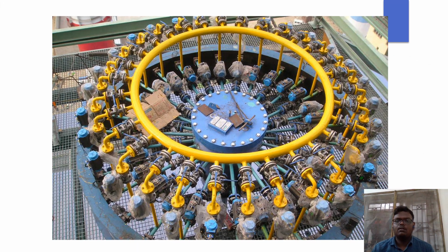In this picture, we can see the pulverized coal injection mechanism. The PCI method is based on the simple concept of primary air, which is the conveying gas carrying pulverized coal, injected through a lance to the tuyere at the mid-bottom inlet of the blast furnace, then mixed with secondary hot air